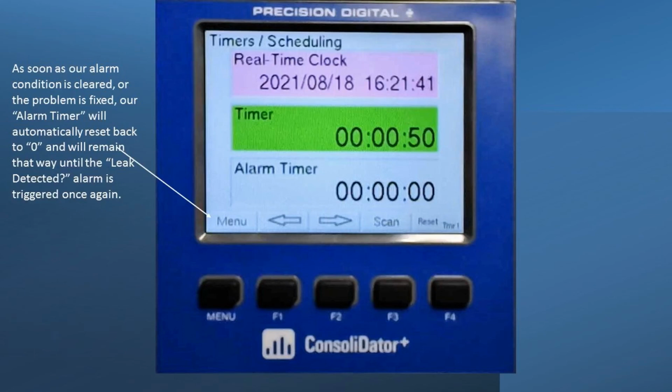Someone else also asked with the pH, it was coming from Modbus, but can I take a direct input from a pH probe? Well, the answer is if it's a 4 to 20, so if it's a 2 or 3 wire sensor, more than likely, yes, as long as it's 4 to 20 milliamps. I'm not a pH probe expert by any stretch of the imagination. I don't pretend to be. But from my understanding, a lot of the probes do have a ton of wires that come out the back. And so from my understanding, it's a little bit of black magic to get those things set up. So I'm going to stick with the answer that if it's a 4 to 20, yes, but more than likely it's going to be 5 plus.